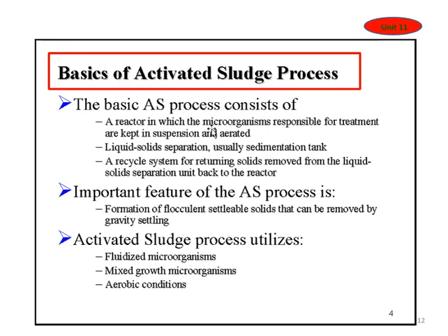Once you do this in the aeration tank, after that you put it in the sedimentation tank, so you can remove the solids, the bacteria, from the wastewater. You will get clean water. And if you want to recycle these bacteria back into the system to speed up the reaction, there could be a recycling system for returning the solids removed from the liquid-solid separation unit, like the sedimentation tank, back to the reactor. So the reaction and the treatment will continue, and the wastewater will be treated constantly.